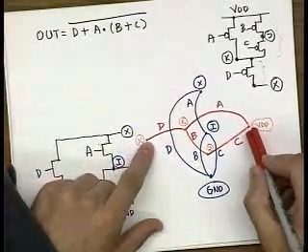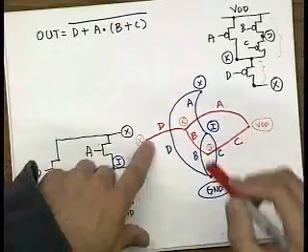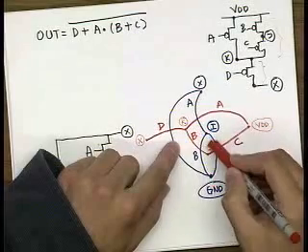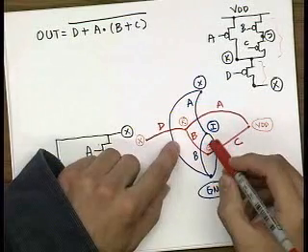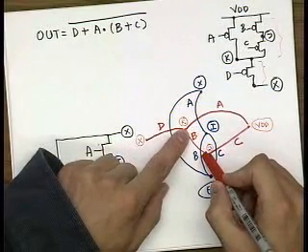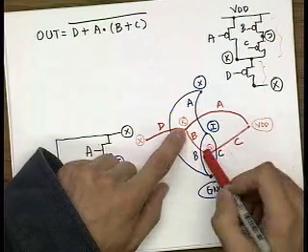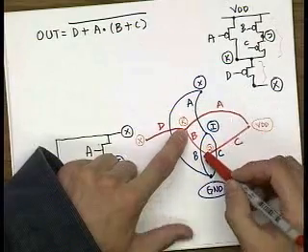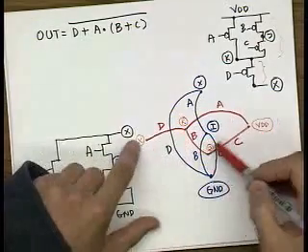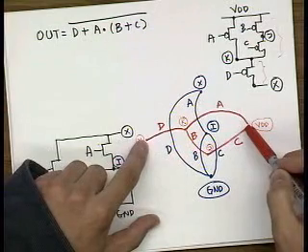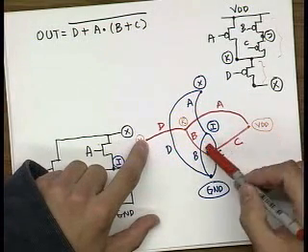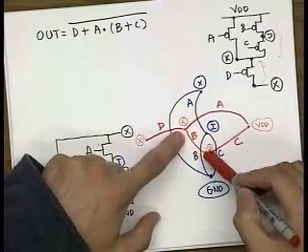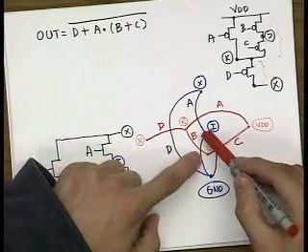Once you have VDD and X, you identify all the isolated regions that are enclosed by the edges of the graph and add nodes in there. So there will be additional nodes in your pull-up network, and you give labels to those nodes. Then all you need to do is connect the graph from the PMOS such that each edge connects two nodes while intersecting with only one edge.